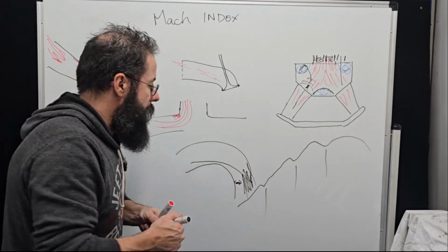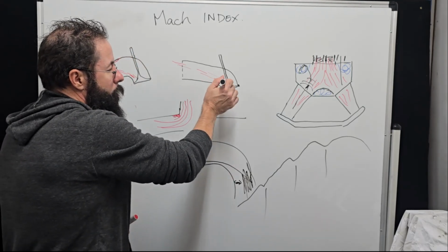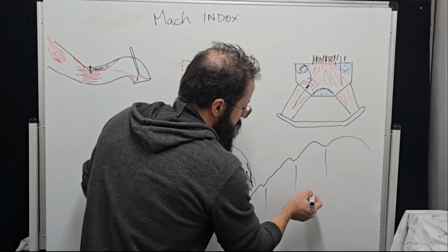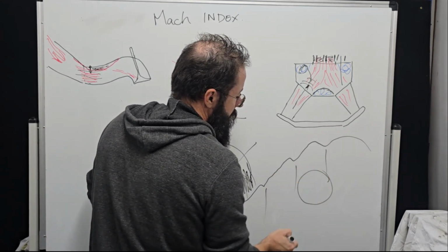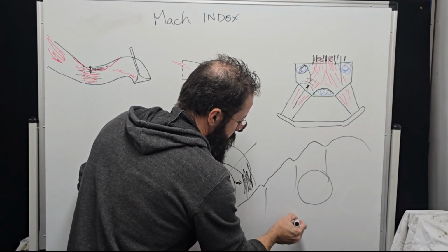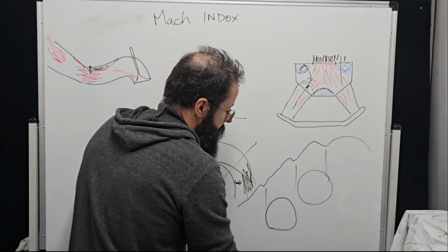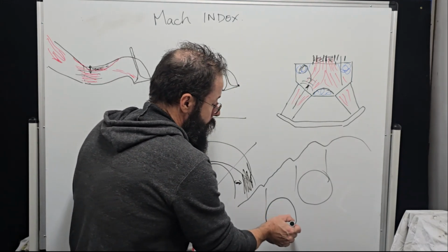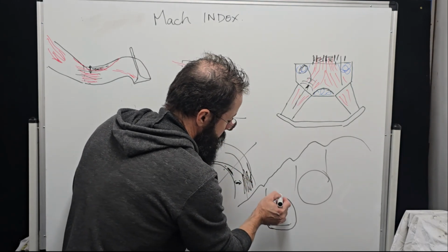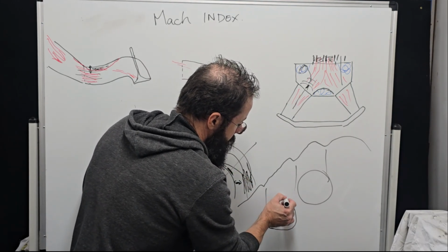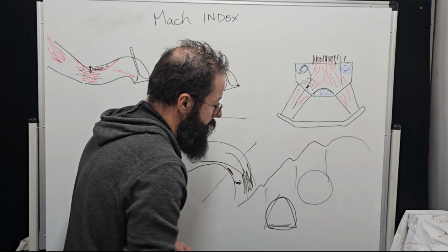And what guys are starting to do now is understand and almost build them like a short turn. So if we cut the pipe through here, rather than it being a round cross-sectional area, it might be something like that. And what that tends to do is slow the airspeed through here and create a better pressure balance. And we look at some of the new Yamaha ports, and they're like that on the exhaust port.